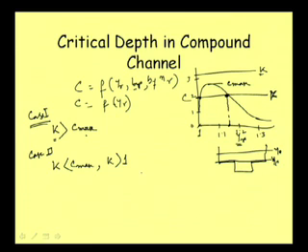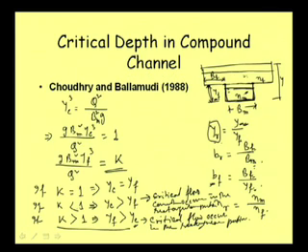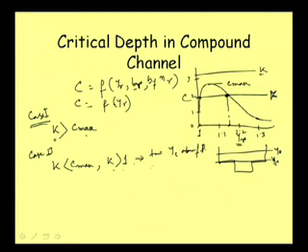So this condition indicates two critical depths above the flood plane, 2 YC above the flood plane. And of course, as K is greater than 1, from the condition we got, there will be another critical depth below the flood plane. So, 2 critical YC above and 1 YC below the flood plane. That also we are getting.